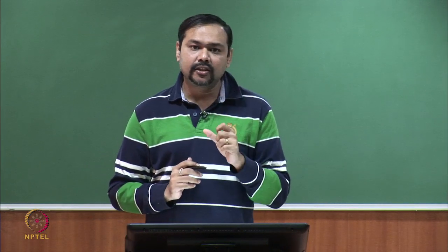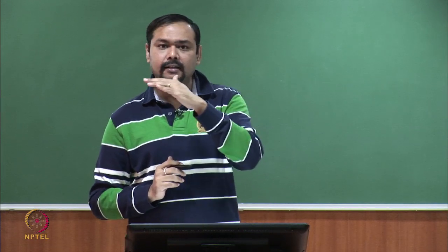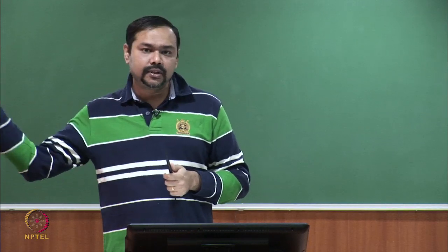Because in a central DC link concept, the ripple part goes through the capacitor. The net energy flows from the rectifier into the inverter side, but the ripple part circulates inside the capacitor. It is not the case here. Okay, this is different.